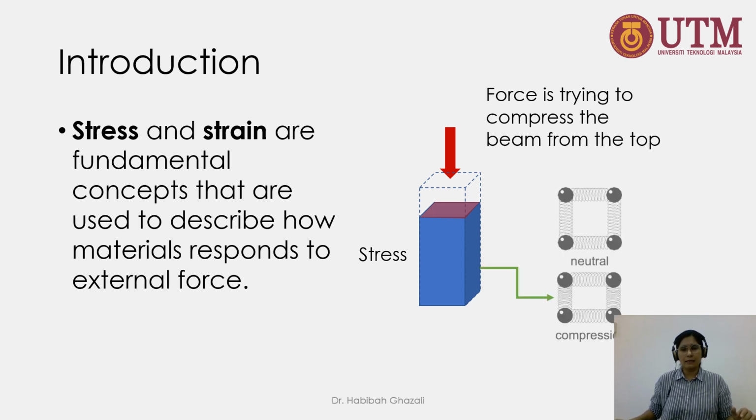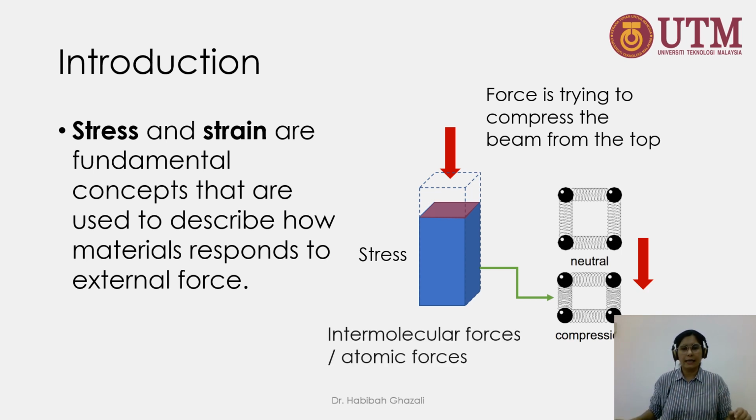So the atoms inside this member, inside these materials, are a little bit too close than what they want to be. So this will result in intermolecular forces or interatomic forces. And if the applied force is within the elastic limit, and if I remove that applied force, these intermolecular forces or the interatomic forces will bring back the structural member to its initial state. So this is a simple explanation of stress.